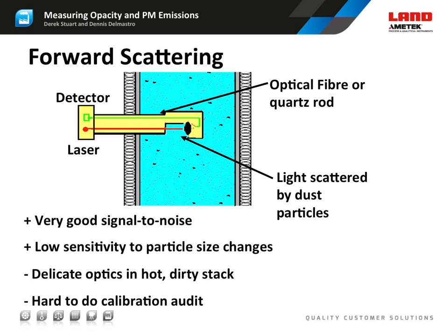For example, a careful design of air purge will stop the stack gases from damaging the optical components. The probe does need to be removed from the stack to perform an audit, which is time-consuming, but it's generally something that has to be done every 3 months and is not unduly bothersome.